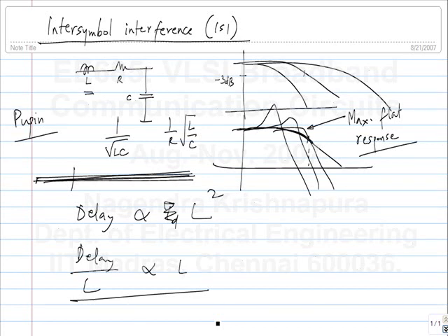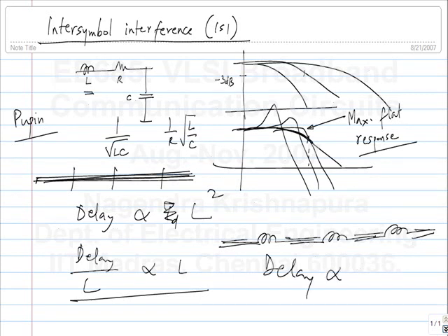Anyway, what this guy figured was he split it into sections. So this is a cable, and then you put these coils in series, and it actually made the transmission much better. Anyway, that also initially was not observed, that you put in inductance and it makes it better. But it does make it better because of effects like this. So it becomes more like an LC transmission line, right? The uniform, the lossless. There is loss in this, but there the delay is proportional to L, and also the attenuation is much smaller. It does work like that. Of course, there is a certain value of L which works. If you increase it beyond that, it won't work.